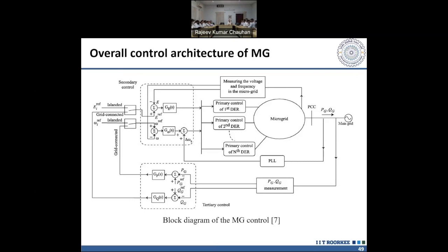Once you have the droop control, naturally your load is increased, your voltage falls down, your frequency falls down. Some phenomenon or action is there which very slightly will compensate this. That is the property of your machine.